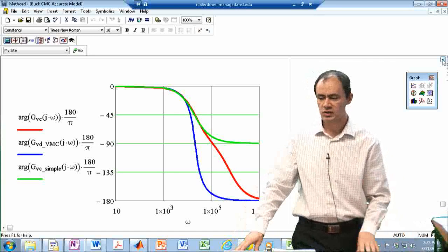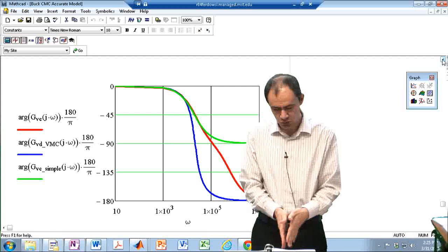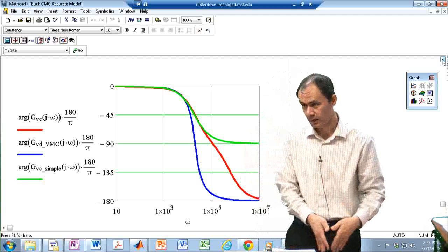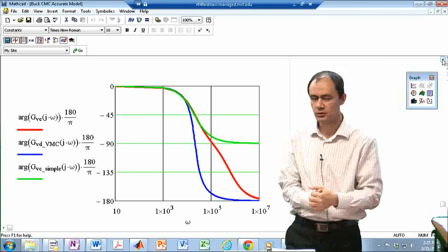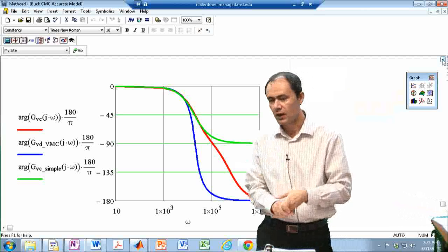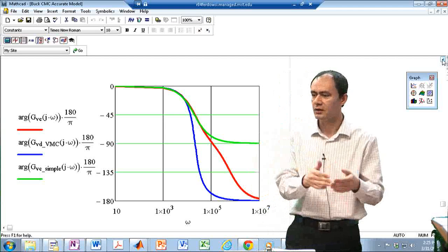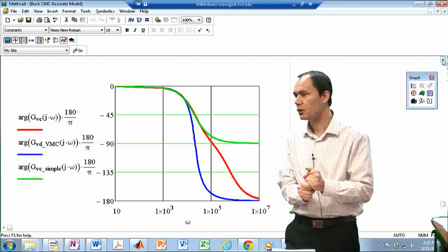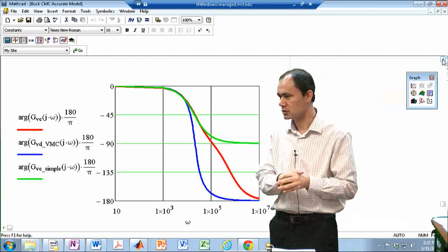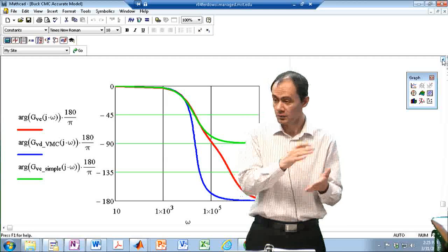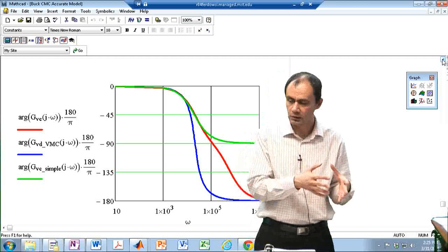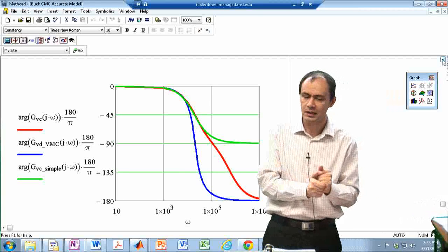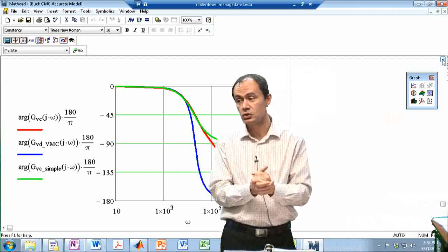Remember what you said are kind of the same thing. You design the inductor and the capacitor based on the ripple. For instance, you say my output voltage ripple should be less than 1%. That maps into the fact that your corner frequency is much smaller than the switching frequency anyway, or that you have a lot of attenuation at the switching frequency. So if you observe those design criteria, you are not going to face a problem where your corner frequency and the switching frequency are very close to each other.